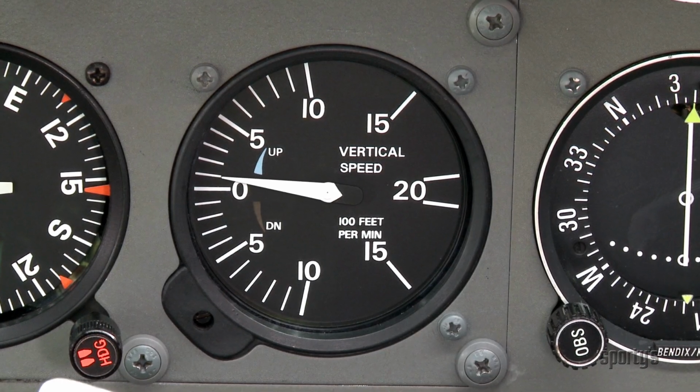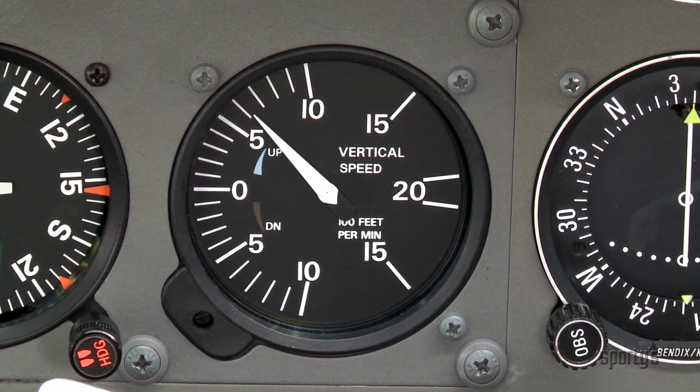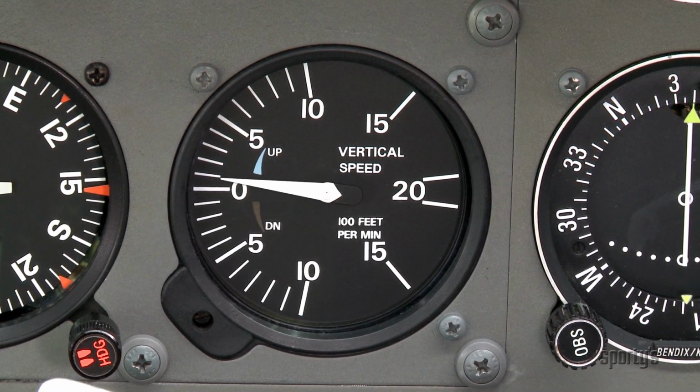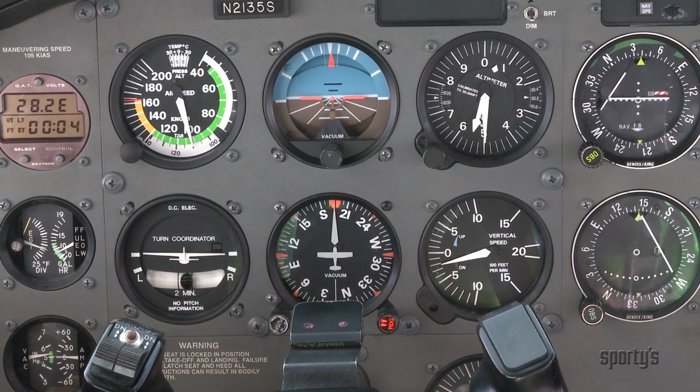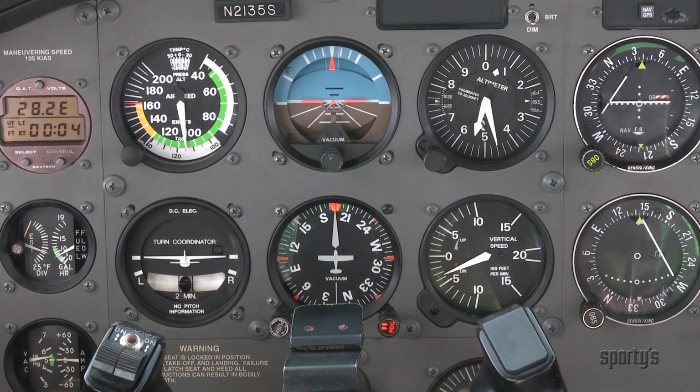You can only be sure of true altitude when the airplane is on the airport surface or is flying in the mythical standard atmosphere. Unless there is an extreme variation from standard temperature, indicated altitude is reasonably close to true altitude. The vertical speed indicator also works from the pitot-static system, measuring the rate of change in pressure and giving the pilot a readout in feet per minute, climb or descent. Just remember, there's a 6 to 9 second lag in the indications of this instrument.